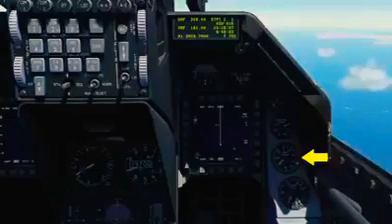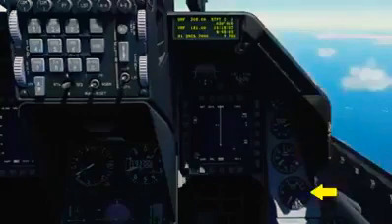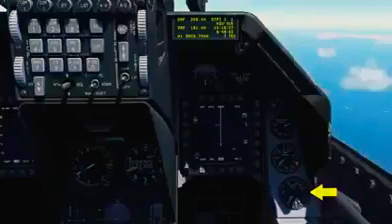from 1 to 110. Note that the speakers still go to 11. The fan turbine inlet temperature, or FTIT, indicates the average temperature in degrees Celsius, and it can range from 200 to 1200 degrees in increments of 100.